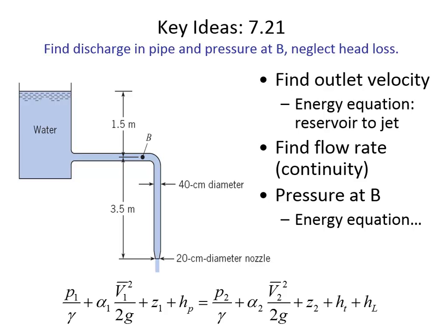The water has velocity and less elevation. Up at the top of the tank, it has more elevation but none of the velocity. So it balances out. That's right, because you have to know what's the velocity at B in order to put a velocity head term in there. And when you're doing the velocity of the orifice right here, for your H term, we go all the way up to the water surface. That's right.